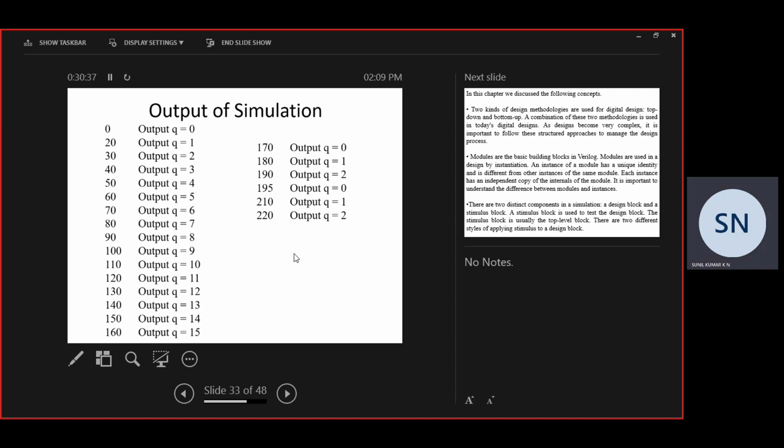So output is sum of 0. C of 0 is the internal output wire. So here I am going to define 2 down to 0 C. Don't get confused. C of 2, C of 1, C naught. So C naught is the output carry. Sum of 0 is the output. A of 0, B of 0, C in is the input. So next one is